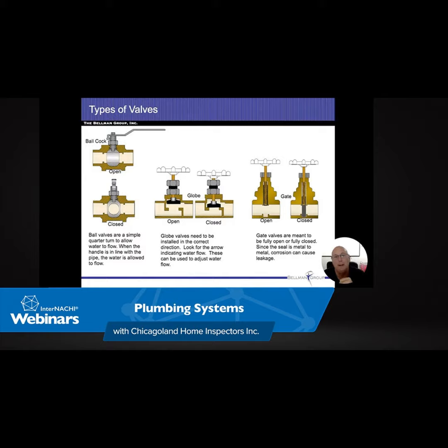This water that's inside these tanks will eat away at the metal. All right, it's going to cause the water tanks, even if they're glass lined, to deteriorate as time goes on. The purpose of this anode rod is all the chemicals that are in the water, instead of them attacking the actual tank themselves, they're going to be focusing all their attention on the anode rod. And they're going to eat away at this anode rod until eventually it's gone.